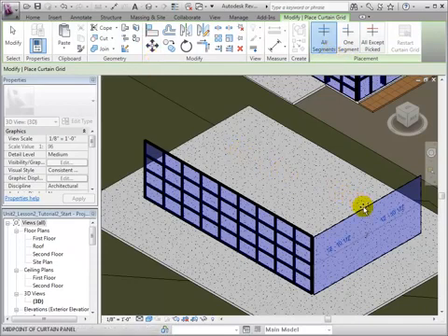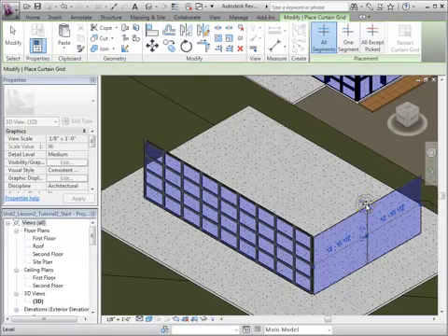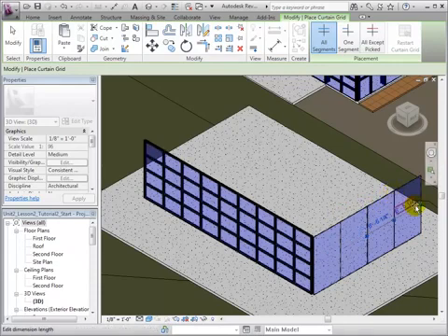Let us start by using the All Segments tool, which will create a grid line across the whole panel. By hovering over the horizontal edge of a panel, we can place vertical grid lines. Revit will automatically snap to key points, for example, center lines. Once a panel is split, we can snap to the center line of the new panel. By hovering over the vertical edge of the panel, we can create horizontal grid lines. Once again, we are able to snap to the center line of the panel or divide the panel into thirds.